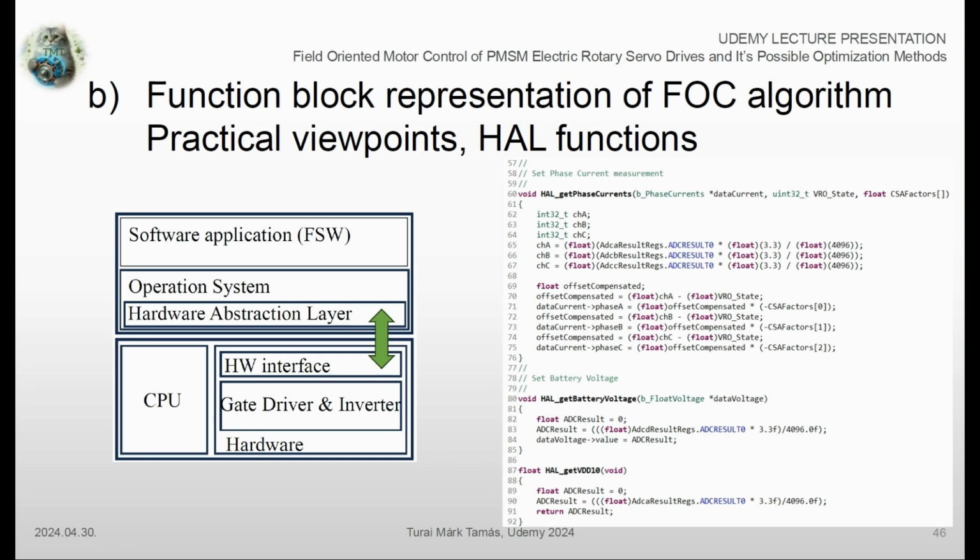The hardware interfaces forward information about the relevant measured physical quantities, usually associated with voltage measurement. Such a hardware interface could be the output of a differential amplifier, which could be responsible for the current sensing mechanism, for example. The measured voltage level in this case is proportional to the actual phase current value, so based on this correlation, the hardware abstraction layer can calculate the actual value of the measured physical signal. So, the application layer only receives measured signals that already represent an actual physical signal value.